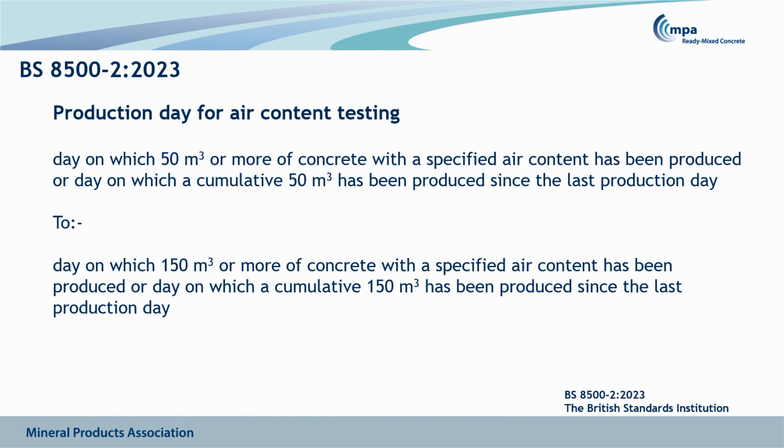Now, production day for air content, this has been relaxed. We've had for many years a requirement where we take an air test, 1 every 50 cubic metres, or when we have a cumulative supply of 50 cubic metres, which is far more onerous than any other requirements for testing concrete. So this has been relaxed to 1 per 150 cubic metres. Although if there is a non-conformity or you're going through initial production, then the test will be 1 per 50.